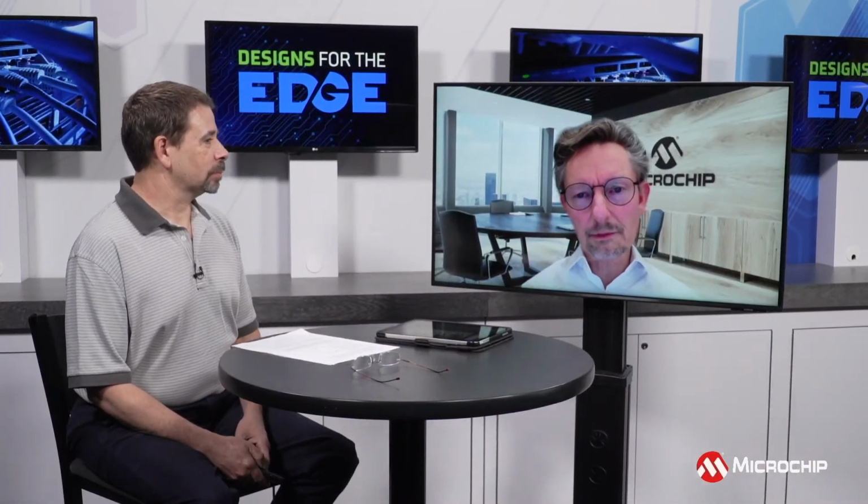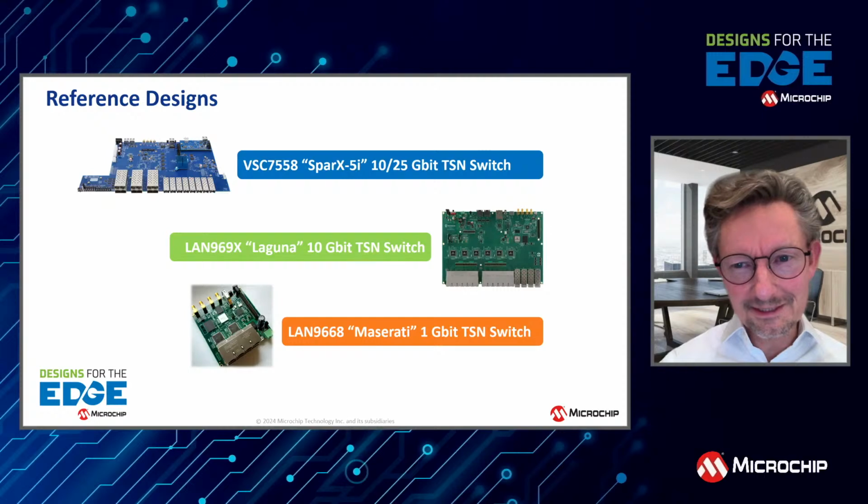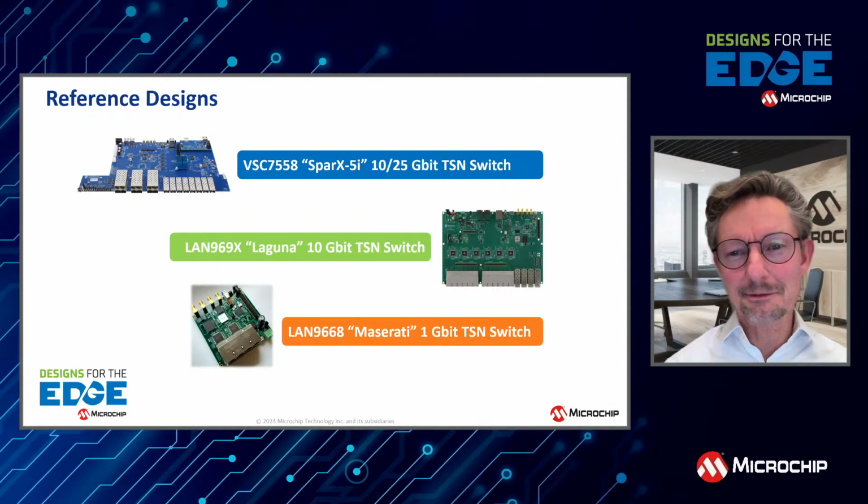Do you remember this resistor here? You have this bleed resistor here. Do you have this capacitor here? Is it the right value? Do you have the VS here close to the ground point, and so on? It's a very, very detailed hardware checkup design manual for the switches. So this is some of what we like to provide to help customers get to their milestones quickly.